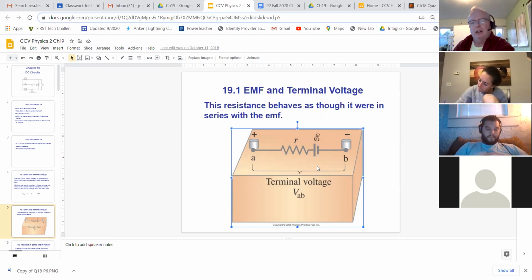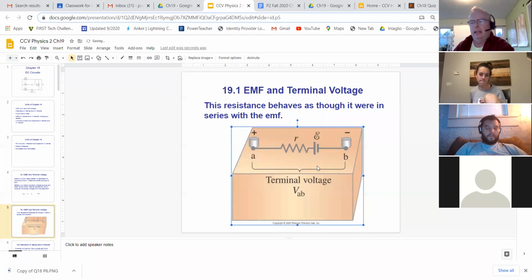so when we ask the car to do something, and I'm sure you've had the experience of when you go to start a car at night, if you have the lights on already and you go to hit the starter, the lights can dim. That's an example of a big load, and it causes the lights to dim because the terminal voltage drops. Here's how we can take a look at how to calculate terminal voltage.